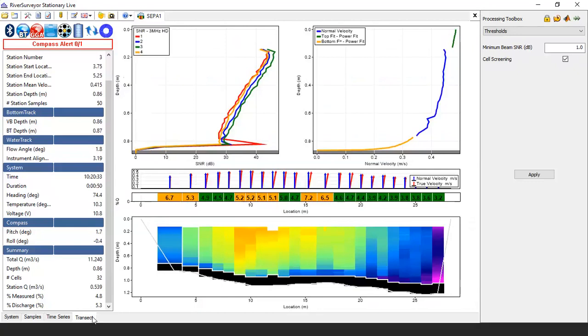So for Bywell, which is a site you know you're going to want to hit a few times when it's high, if you know that you get a really representative discharge if you get one vertical at 5 metres, one at 25, one at 40, and one at 75, whatever, you could figure out the key locations across the river. If you really have to hit it fast, get them in the bank, and then infill or just move on. But you could do that for any site where you've previously done a high flow gauging with section by section or stationary. You could do that analysis and figure it out.